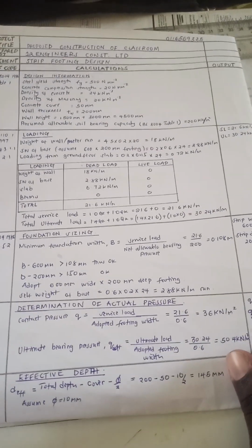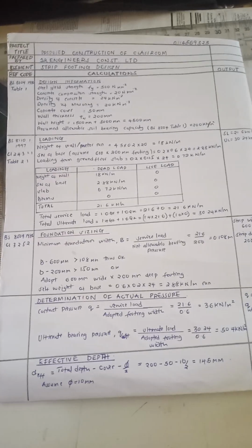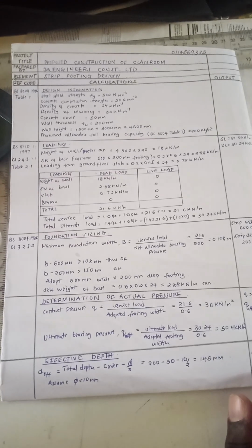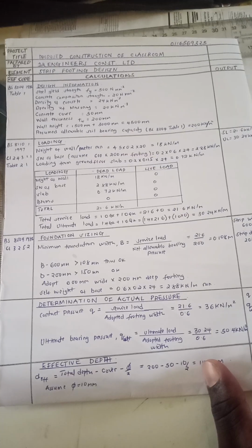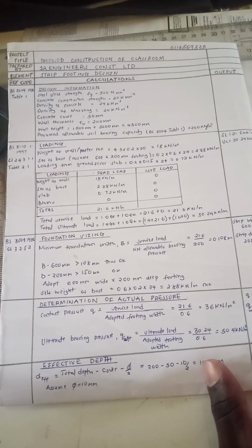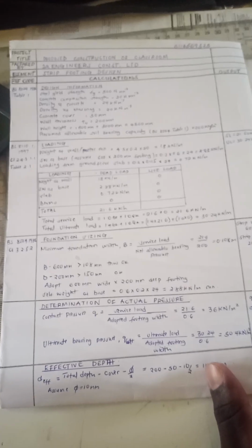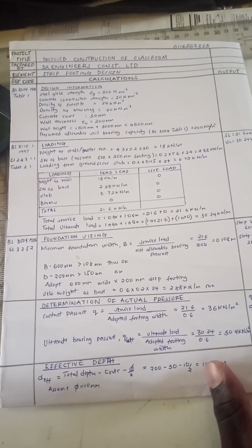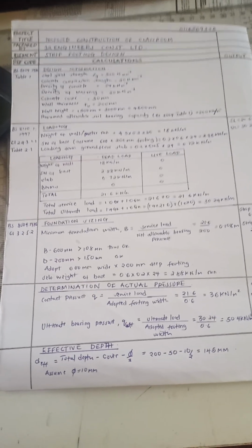that way. Then you move to calculation of your effective depth. Effective depth for the footing is similar to that of a slab, determined in the same way, which is the distance from the top part of that element to half the bottom of the reinforcement.